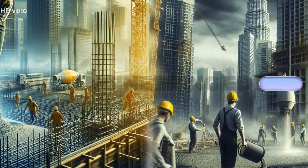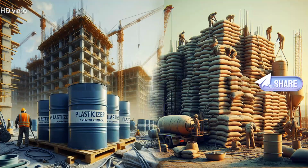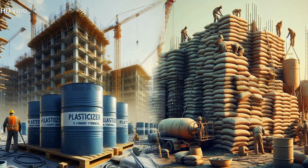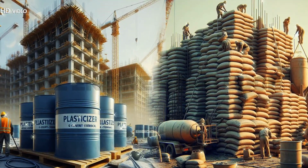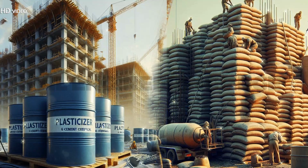G. Mass of fine aggregate equals volume of all-in aggregate times volume of FA times specific gravity of FA times 1000, equals 0.74 times 0.451 times 2.46 times 1000, equals 821 kilograms. Summary: cement equals 315 kilograms per cubic meter.